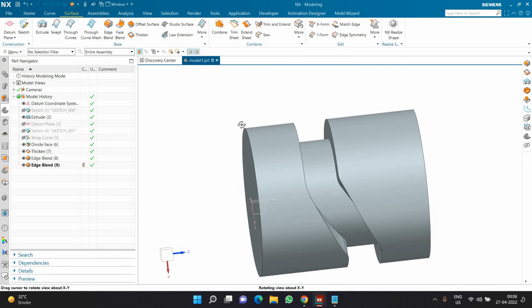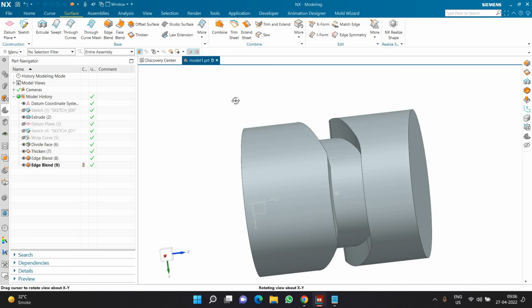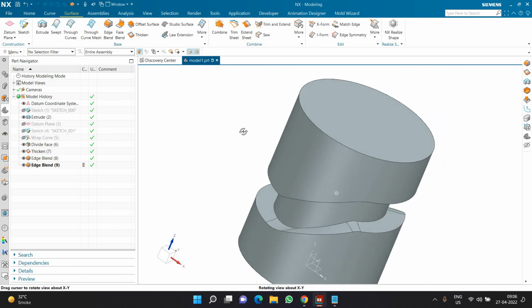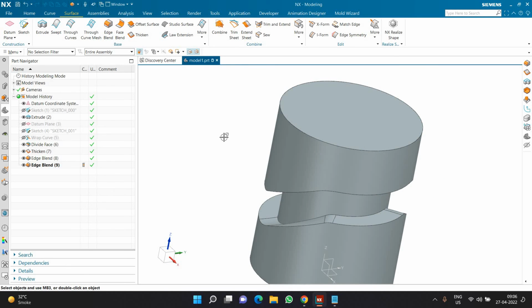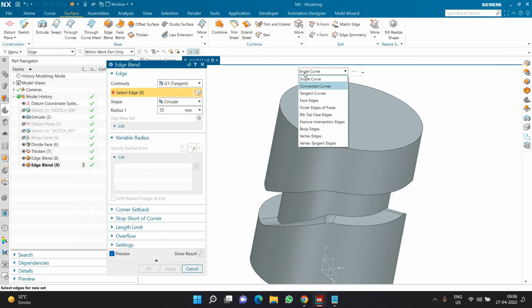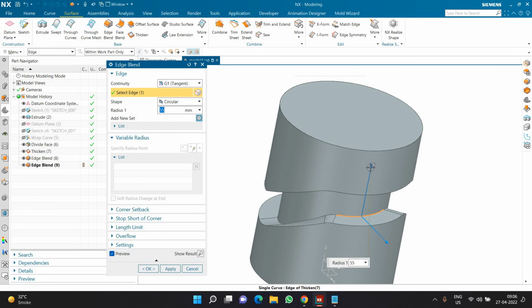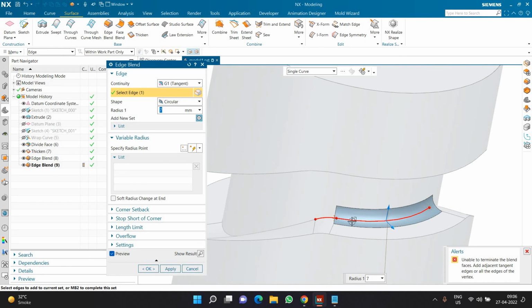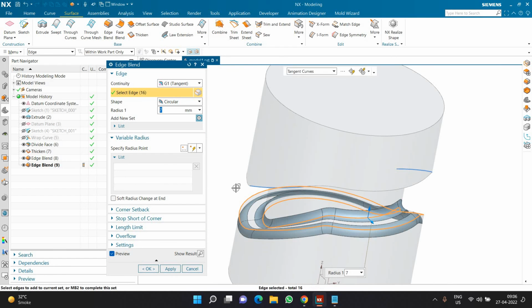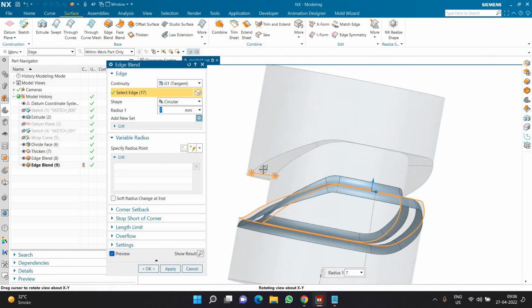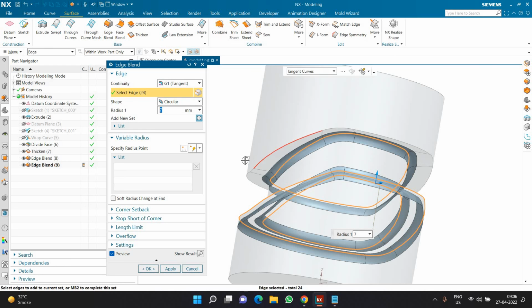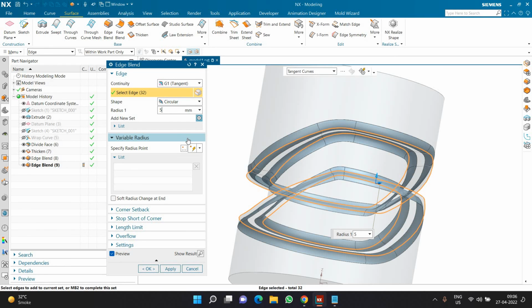So if I wrap this around, this is how the entire part is going to look. This will give me a proper geometry of a cam if I'm trying to create one. The only thing is there are different options which will help you to create this particular inner geometry even more perfectly, and that will give you a much better result. Let's say I'm creating a smaller radius here onto a tangentially connected surface over here and over here as well, just to increase the aesthetic value of the design. So here I'm creating the two rounds.